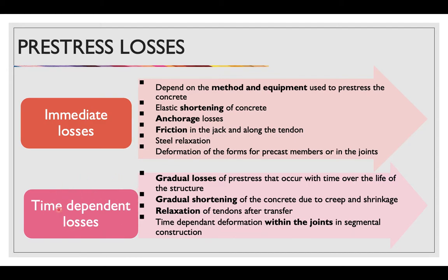Then we have another one, which is the time-dependent losses, right? So this will consider the gradual losses of pre-stress that occur with time over the life of the structure, right? So it does not happen immediately after the pre-stress force has been applied to our structure, but it is the losses that occur over time, right? So it takes a long time during service of our structure, then it will actually be subjected to this type of losses, right?